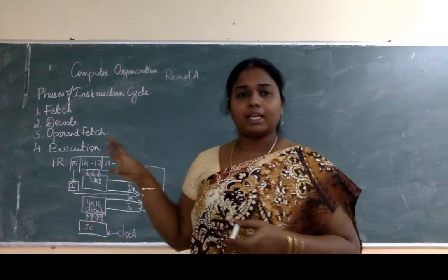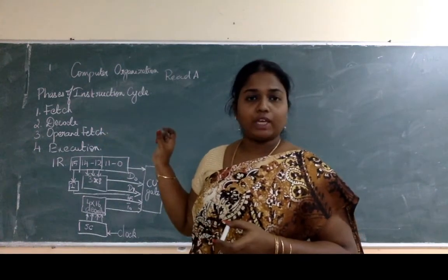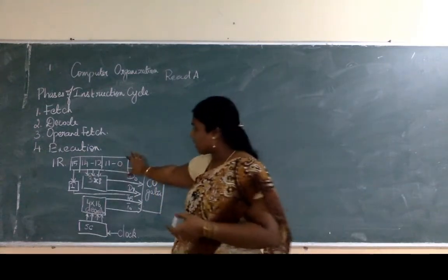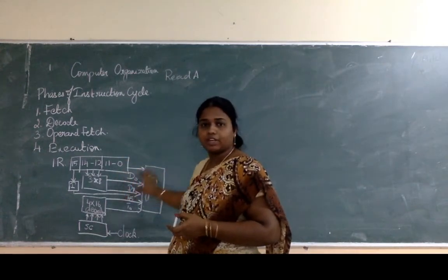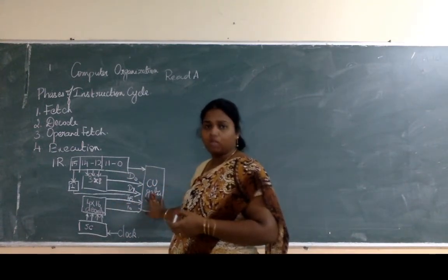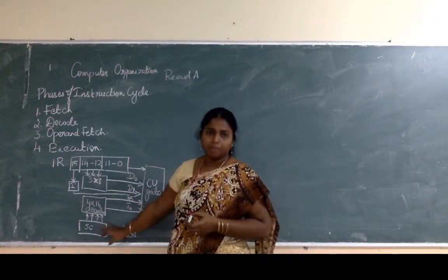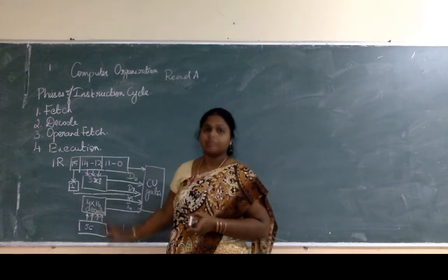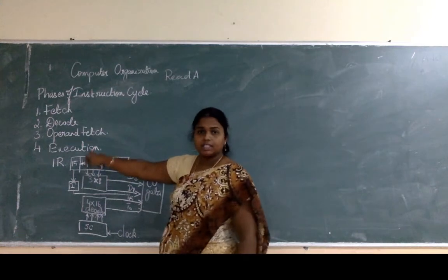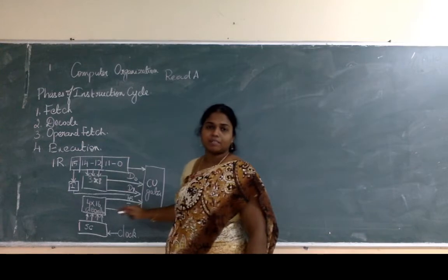So with this in mind, we are going to see how the operand fetch and the execution phase works in a normal computer. So I have the instruction set, I have the decoders that generate D0 to D7, and I have the decoder that generates T0 to T15, and I have the sequence counter that indicates the completion of execution of a single instruction. So after every instruction finishes its execution phase, the sequence counter has to be cleared so that it can start generating timing signals back from T0.